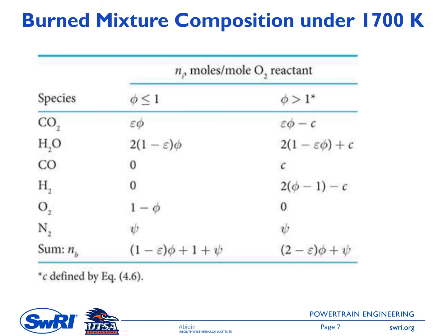When we solve that equation for Ni, we will get Ni for burned gas species in this table. You can see here that the composition is differentiated according to the value of phi. The second column here is the composition when phi is less than 1, so it means we have a lean mixture.